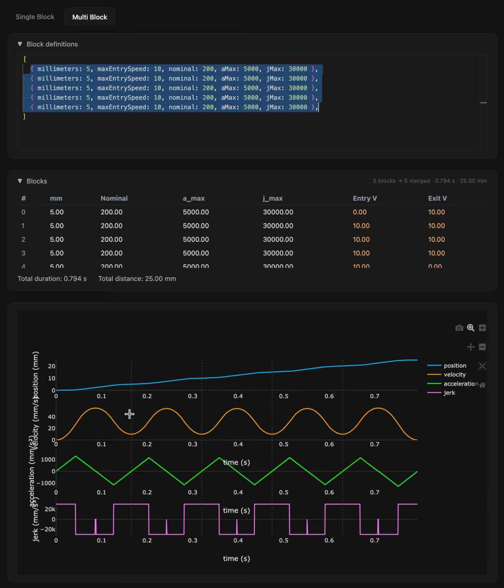If we were reducing acceleration when we reach the block, then we can reach a speed, but only if that end acceleration is the right one, and so on. And the issue is that these envelopes that we get at all the junctions are not a set that can be defined with a single equation. They are hard to intersect.